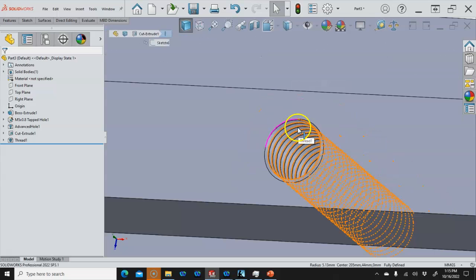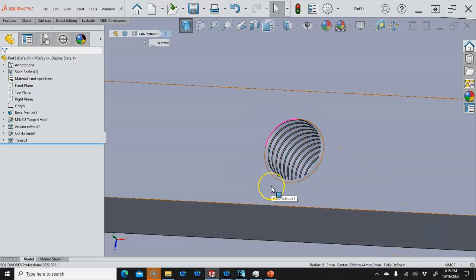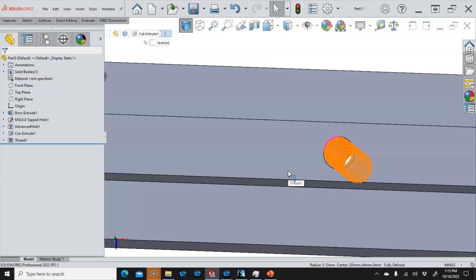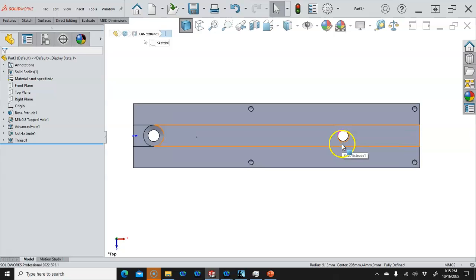So for the machining, I would identify which one of these will act as a center, verify it against the drawing or against the geometry. If it's a translated file, it makes it a little more difficult, but putting the minor diameter in place, at least a little bit bigger than the major diameter, I would just make that a straight hole if I couldn't modify it otherwise or suppress it.